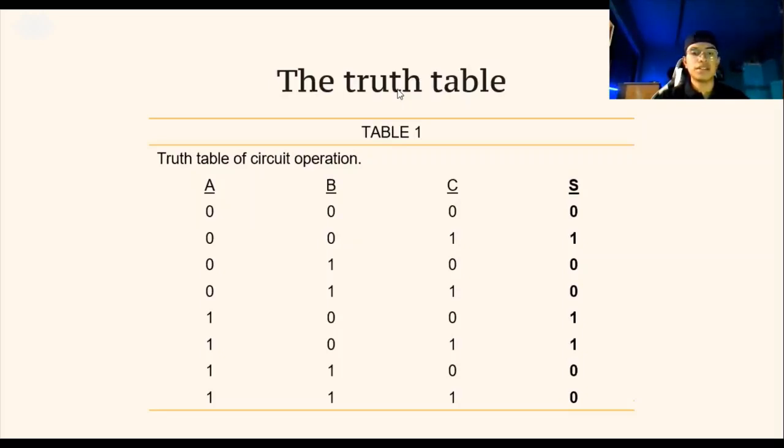As we can see in the truth table, we have three inputs, A, B, and C, that correspond to start, stop, and change of rotation of the motor respectively, generated by the push buttons. We start with the state where none is pressed. The buttons are inactive, so the circuit is in its initial state and the output of the logic gate is 0, and no voltage or current arrives at the transistors.